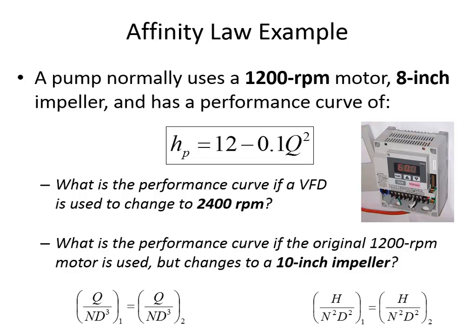And so the advantage of this larger diameter impeller is just that as the flow rate increases, it loses its pump head more slowly. So if you were going to go with a high flow rate, then the larger diameter impeller would be the way to go. If you're going to be pumping to a higher elevation, then it would be better just to increase the rotational speed.